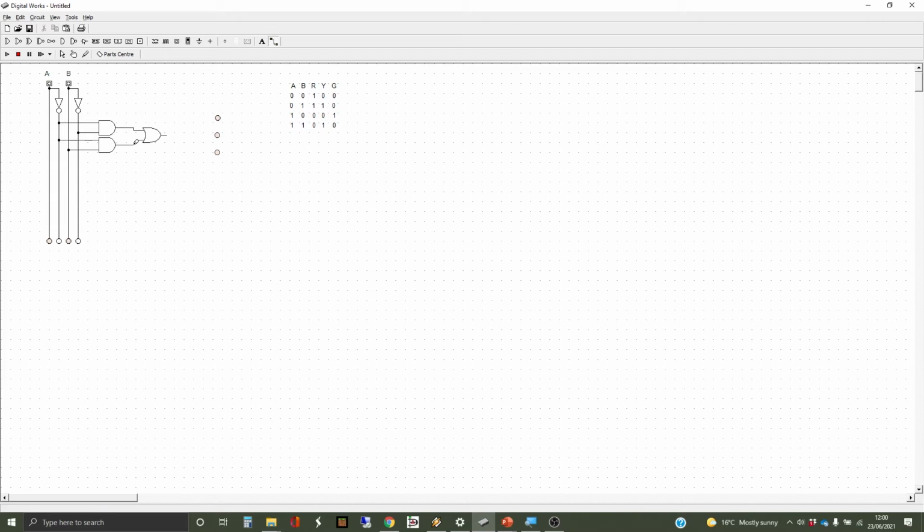And this is how you go from a truth table to a circuit: you have a set of lines representing your binary inputs, and then for however many conditions you want to be true, you use AND gates. And if you've got more than 2 inputs, you might need multiple, like 3 or 4 input AND gates here. And then you take all of the ones that you might want into an OR gate to connect them together, or multiple ORs if you need them. And that's going to be our red wire there.